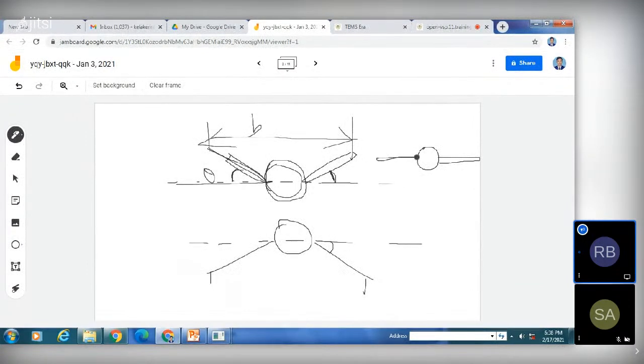There is no anhedral or dihedral angle, which means the wing has not been placed in an inclined form with respect to the axis I have shown. If we place it with some inclined angle, we call that angle the dihedral, and opposite to that, the anhedral angle.